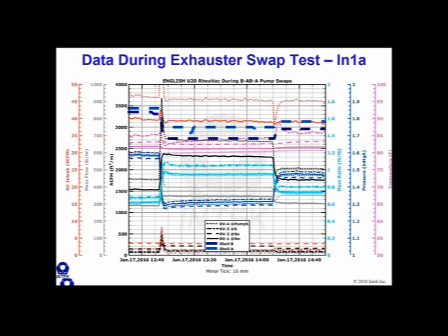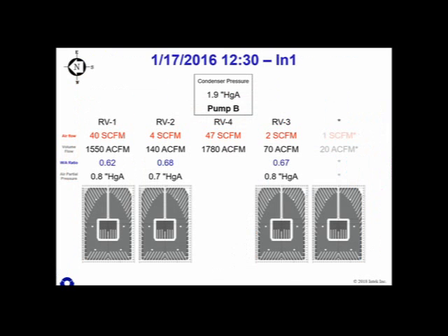So let's take a look at the data here. Anyway, that's what we found. The takeaway here is that there's air leakage somewhere, probably on this wall. It's not from up high in this shell. It's probably on this wall coming in through one of the drains. And so they can limit their air leakage search to this wall and all of the systems attached to this